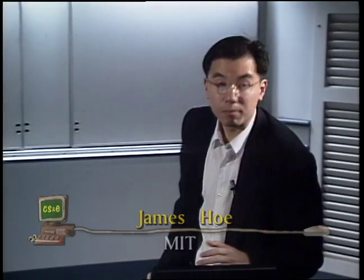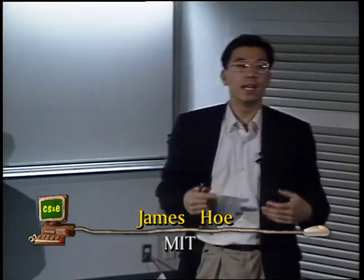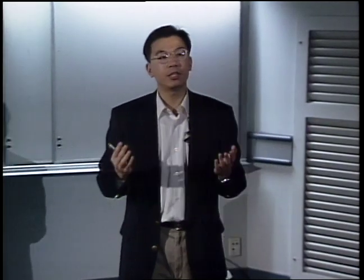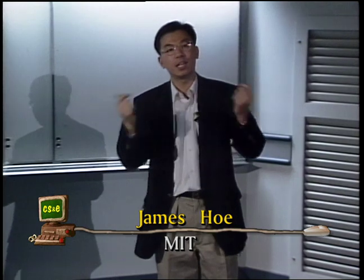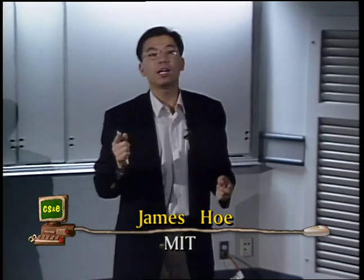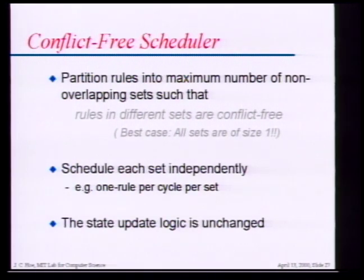And we can take advantage of this theorem in a more aggressive scheduler. So to build a scheduler for this, we have to first analyze the conflict-free relationship between all pairs of rules. And computing the conflict-free relationship is actually very expensive. So in my compiler, we substitute in several rounds of more conservative tests. But in any case, once we have found as many conflict-free relationships as possible, we can then partition all the rules into the maximum number of non-overlapping sets, such that if two rules belong in different sets, we know they're conflict-free. And once you've done this partitioning, we can schedule each set independently, right? Because whatever one set selects will be conflict-free with the selection made by all the other sets. That's guaranteed by this partitioning algorithm.